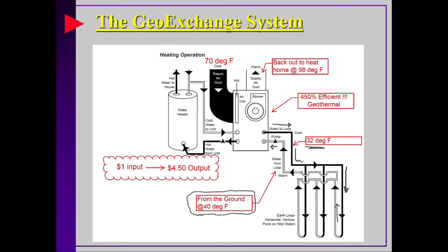And in that area, it'll vary a little bit. If it's really, really high demand, this 32 degree water, depending on the length of runtime, could be 32, could be 30, could be 25. If the system or the loop field is not designed correctly, you could easily see that 32 become 20 and 18. That would be an indicator that you've got a problem. You don't typically want to see this temperature get too cold, or that's indicative of issues, whether it's flow rate or something that wouldn't be right.